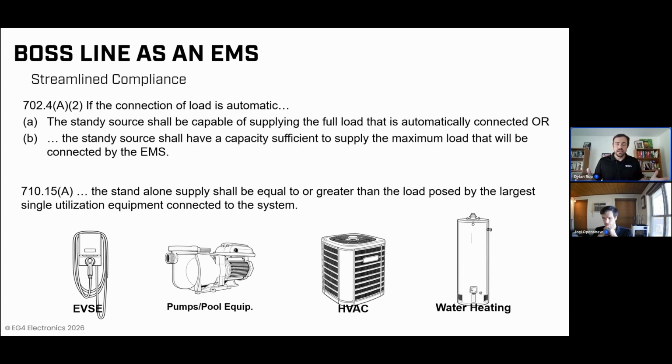Now, I will say, certainly we see that this code is not enforced everywhere. It's not actually a new addition to the code, but it's not stringently enforced everywhere. However, we have some areas, North Texas being probably the one I'm most familiar with, where this is a requirement. And it's a reason why a lot of smart panels are sold in those markets. This gives a really streamlined compliance path for those areas to deploy energy storage systems without having to add a bunch of additional components and technology to be compliant there.